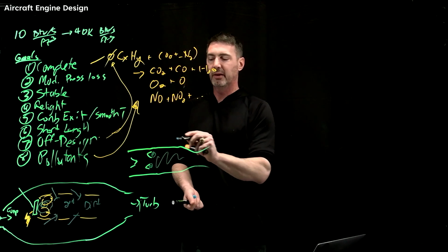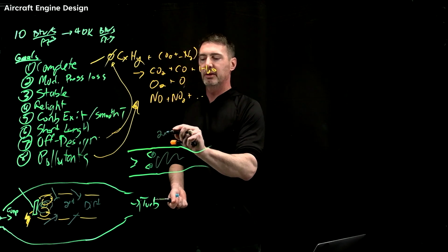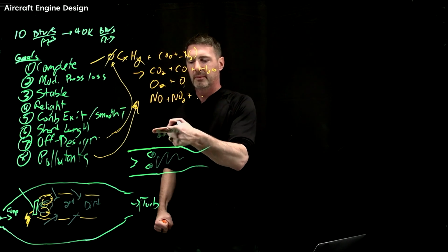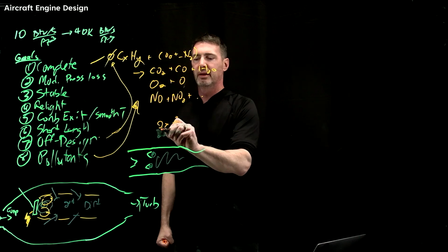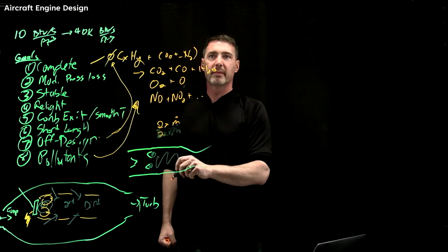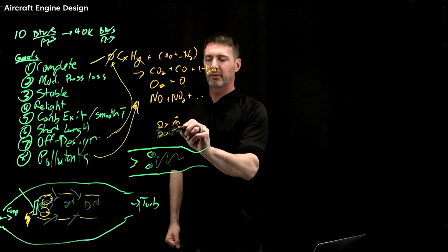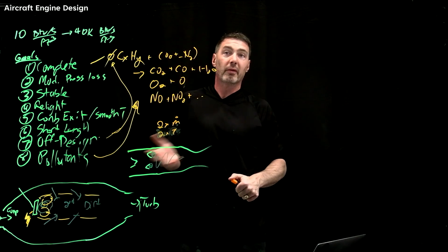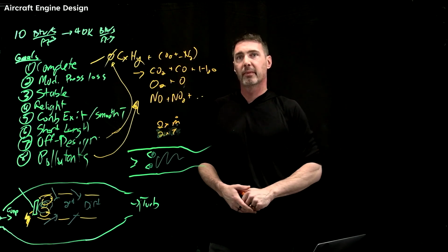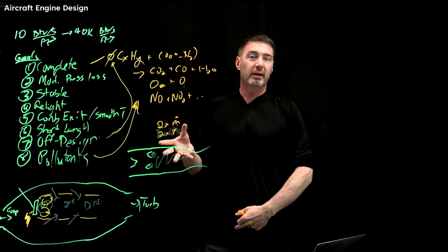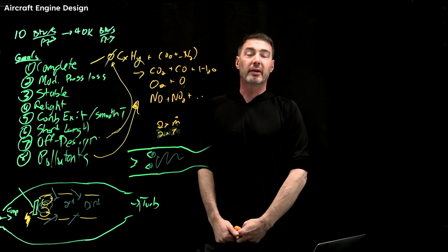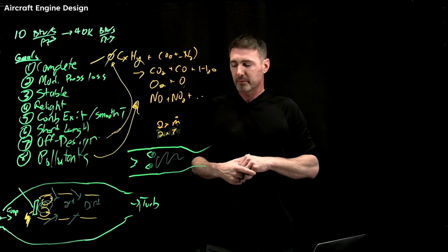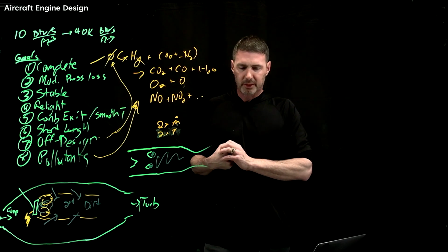Now, usually what happens here, let's say you might 2x your mass flow rate, and maybe even more, but you're going to likely double your thrust as well. And so usually it's a combination that works well for those military missions, driving down from the vehicle level, especially for aircraft that need to get past the sound barrier. Getting past the sound barrier without an afterburner, doing it fully dry, is challenging. It's possible, but challenging. They've really got to be pretty powerful engines.